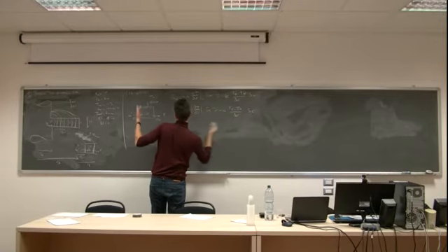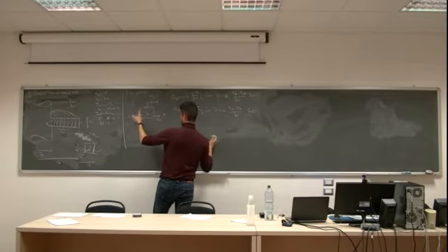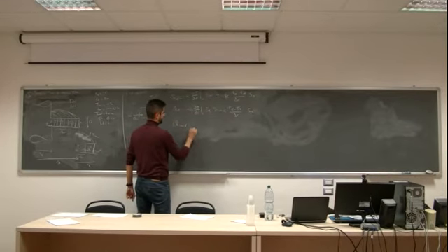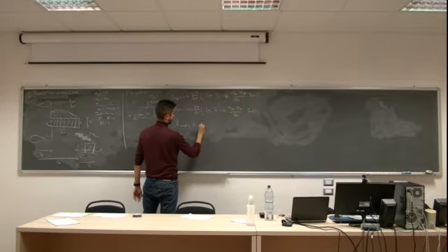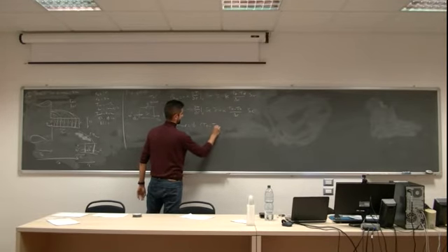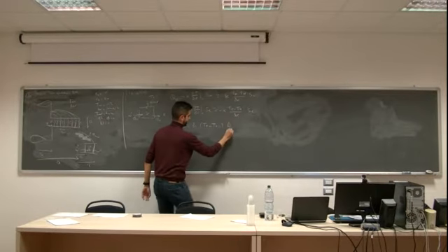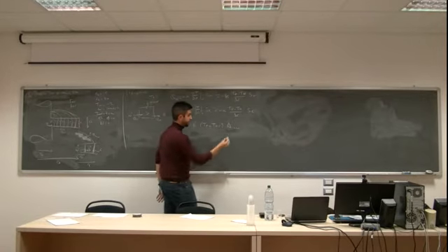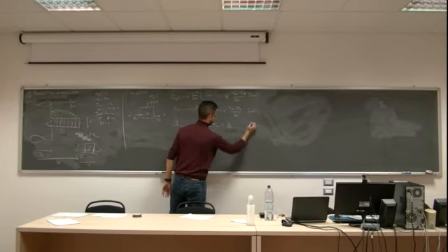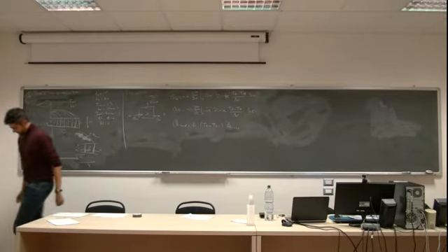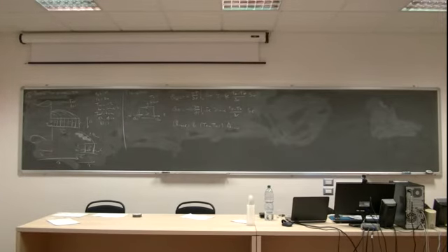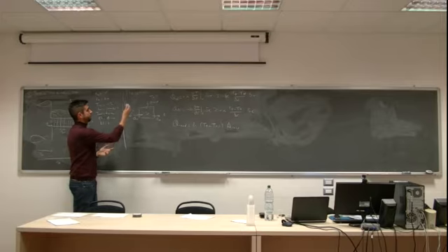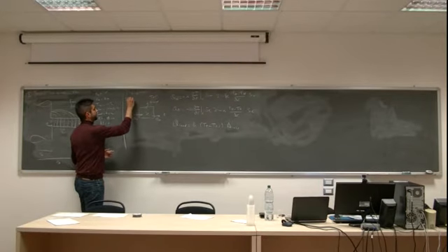Now, another thing that we have related here is convection. H multiplied by (Tp minus T air) multiplied by the area of convection, which depends on the node also. That will be 1 or 2 or whatever. Questions? No? Good. So, let's do, from the energy equation we got this, right?